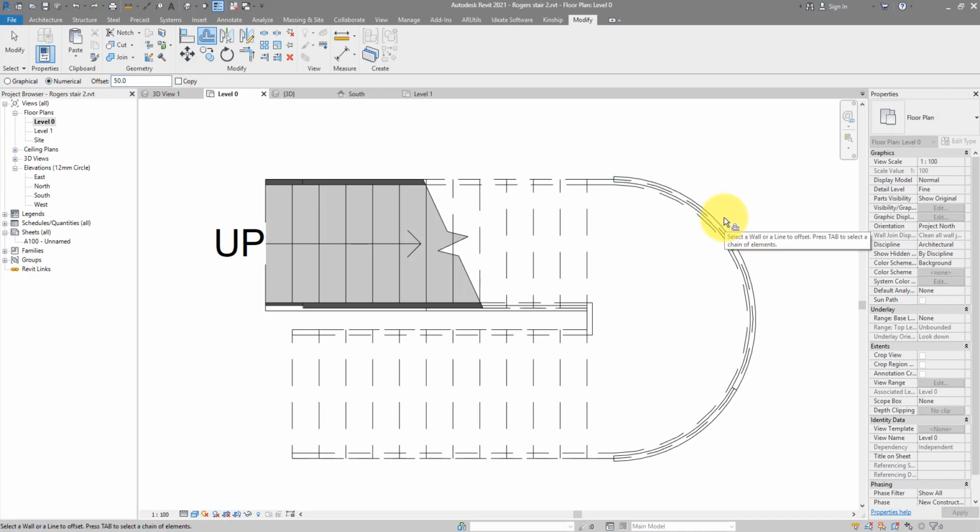Untick copy. And then make sure you don't offset the individual wall panels. If I do this for example, only that one single panel is affected. Let's undo now. And this time, make sure we get the dashed line at the center of the curtain wall. I can now click once, and it's done it.